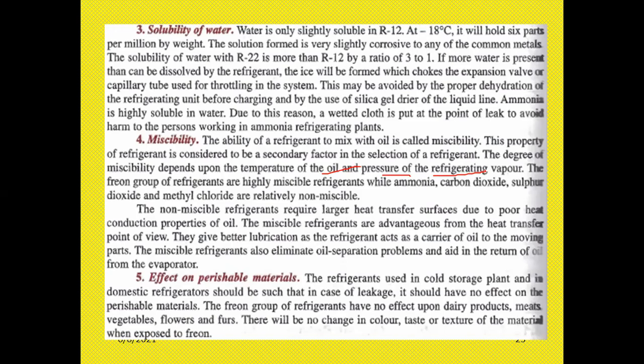So the degree depends upon the temperature of the oil, what type of temperature you are maintaining, and the pressure of the refrigerating vapor. The Freon group of refrigerants are highly miscible, while ammonia, carbon dioxide, sulfur dioxide and methyl chloride are relatively non-miscible.